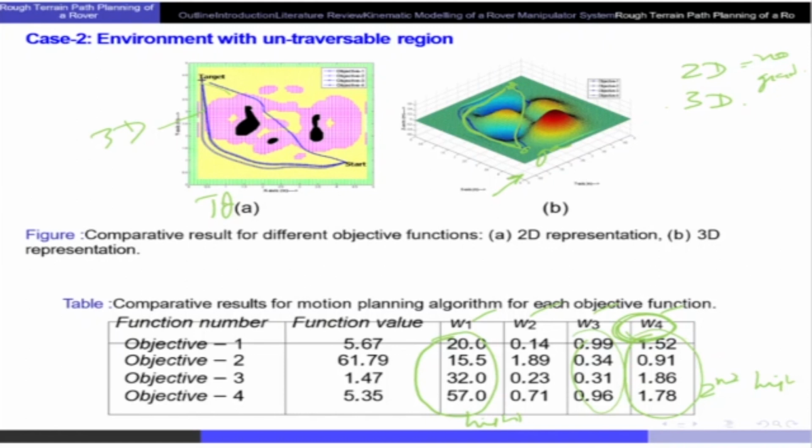That means 2D potential field cannot be applied directly to 3D. Because if you don't include the gradients, the robot will simply find a path which is the shortest path. But that can take very high energy. Okay, because they start climbing all over. So if you include the gradient forces, what happens is that we get very low energy and you get a very safe path. So today we looked at